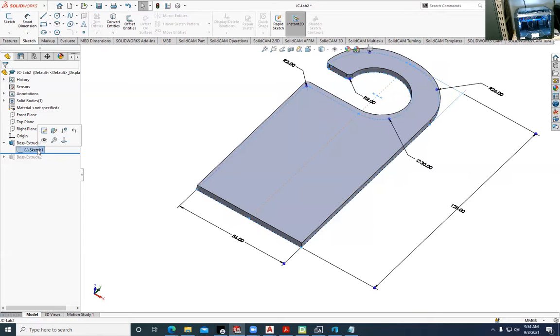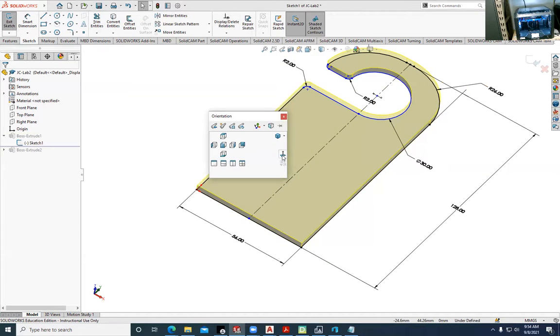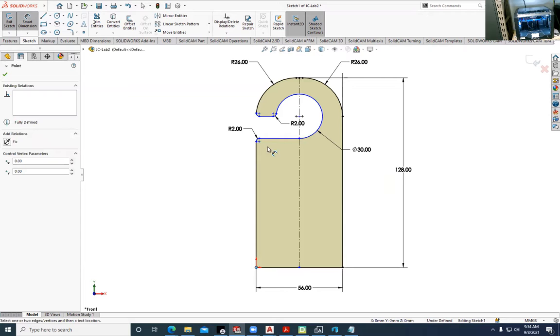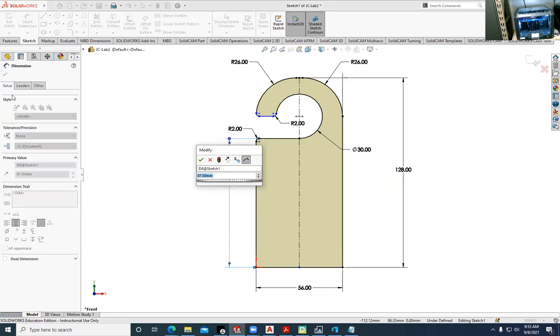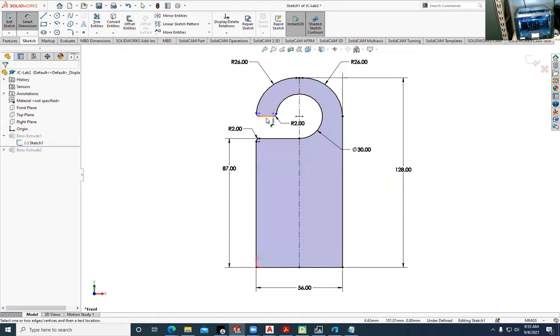And so here's what I created from a sketch. And it's really the same thing. I need one more dimension to fully define it. But if I take a top view of this, here's my part. The reason it's blue is it needs a smart dimension to the origin. Whenever they're blue, it's typically because it doesn't know where it's at. And so if I put one of these dimensions on it, it will usually make everything fully defined. I probably need another one here.